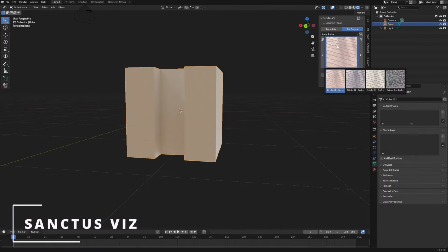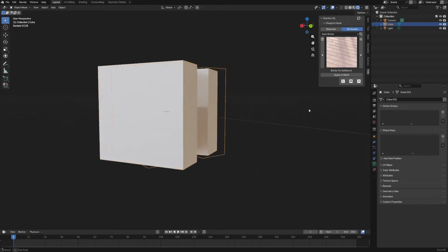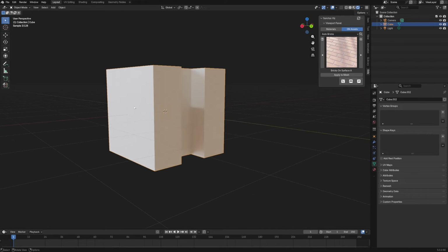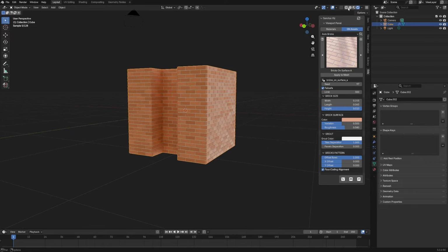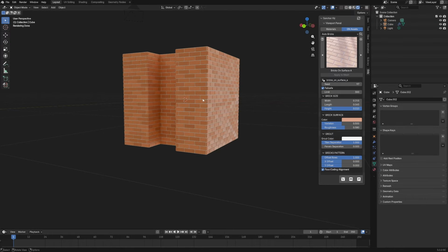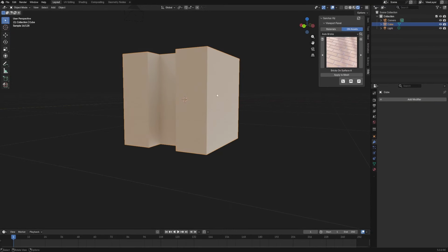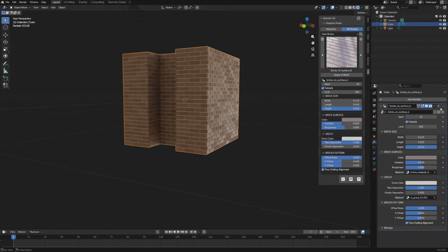also. We have auto bricks. That's a quick way to add bricks to a geometry. Again, this is for flat surfaces. If we use it, we can see this generates real geometry. To change the asset, you have to remove the old one. I'm working on having this automatically, but for now you have to do this, and you can apply the other one.